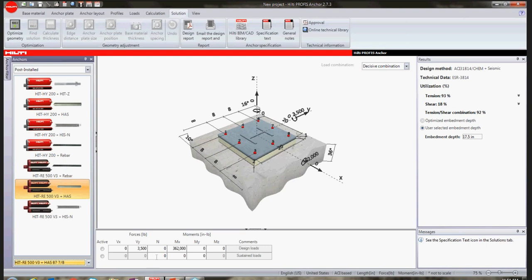input the omega naught factor into the loads that I'm going to use. But if you hadn't, you could click yes, and then input your factored loads, so revise your factored loads to consider that omega naught factor now. So we're just making sure that we've accounted for these loading conditions when we select this option, because 3 out